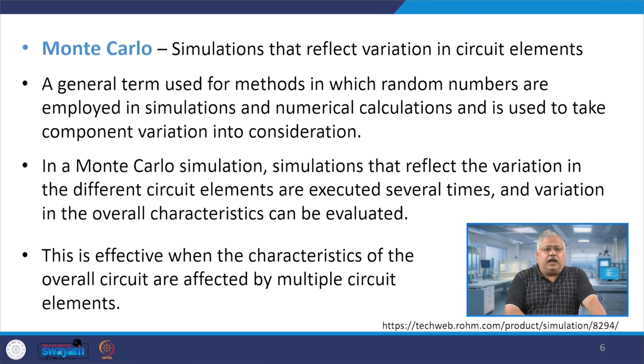Okay. There are other methodologies which people have used, and especially these are used for circuit simulation purposes. Now you could appreciate one important point. Let us suppose I have a MOSFET being used. This MOSFET is basically a 4 terminal device, assuming source, drain, gate, the channel length and width, and there are doping concentrations and so on and so forth. Now what happens in reality is, when you take this MOSFET and use it in a circuit, there might be variations in the circuit elements.